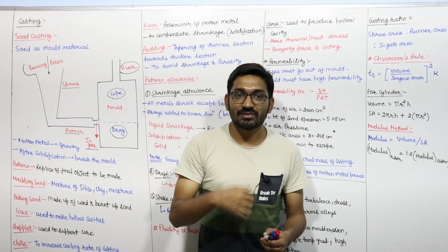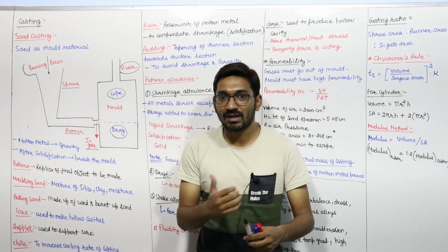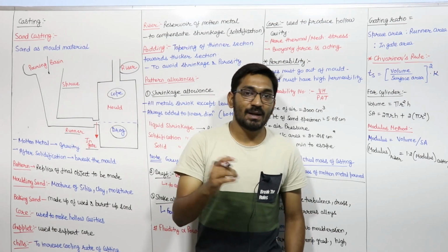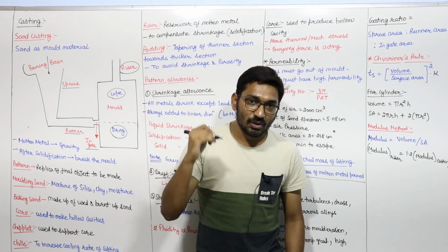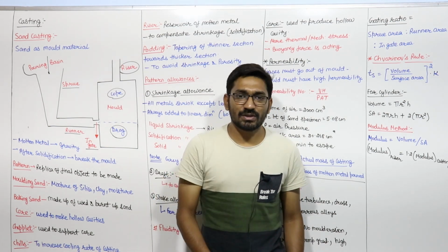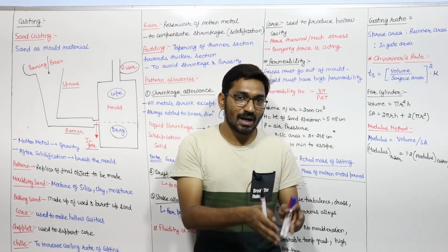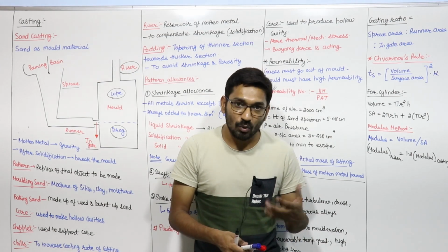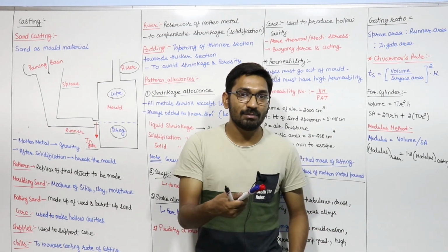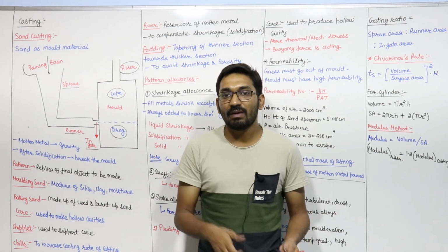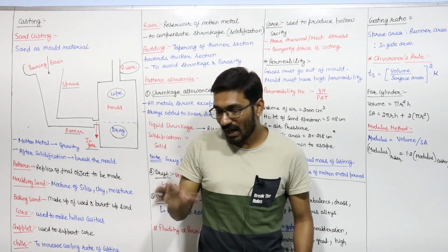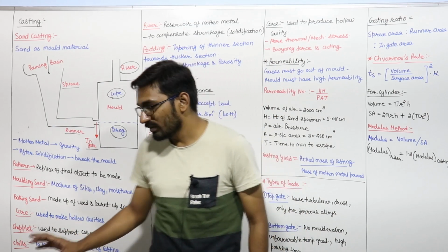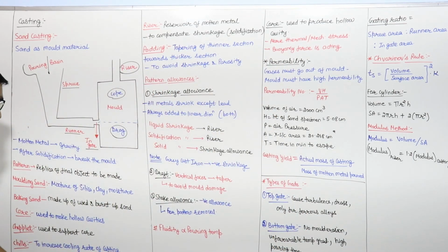product depend on the grain size, right? How much strength, how much toughness, what is the hardness, what is the ductility, all properties will depend upon the grain size. So the grain size will depend upon the solidification time, and so in casting, solidification is the most important thing. If at some part the solidification time is very less, or very more, it takes more time to solidify. But if you want to increase the solidification rate at that particular location, we are using these chills. So chills are used there to increase the cooling rate.